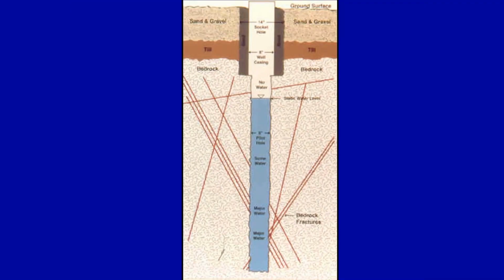There may be times when you are drilling a rock well that you encounter fractures which are unstable. It is rare, but there are times when a well screen has to be put in that section of instability in order to make sure that a pump is not locked in by debris falling on top of it, or enough debris falls in that you reduce the yield.